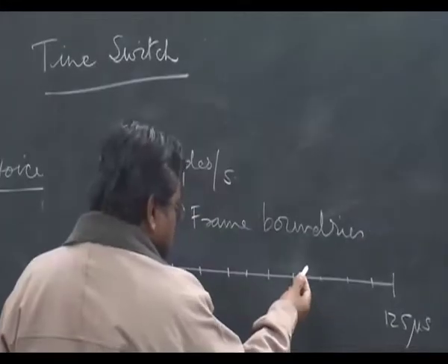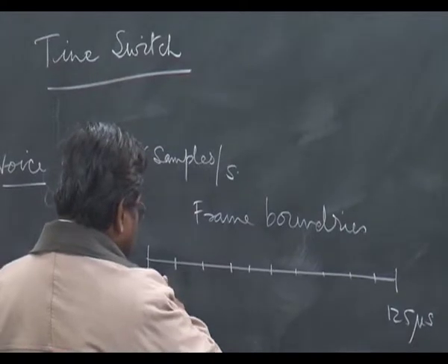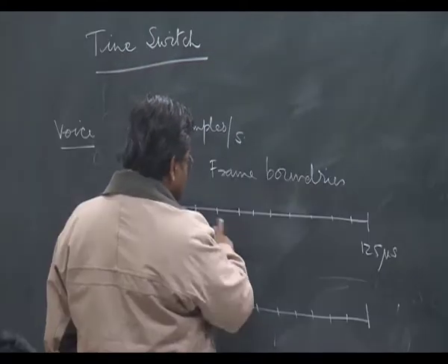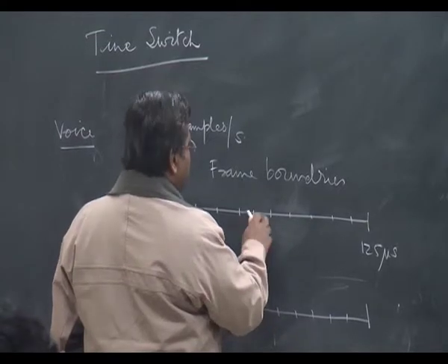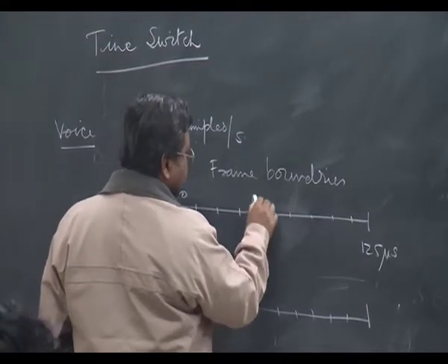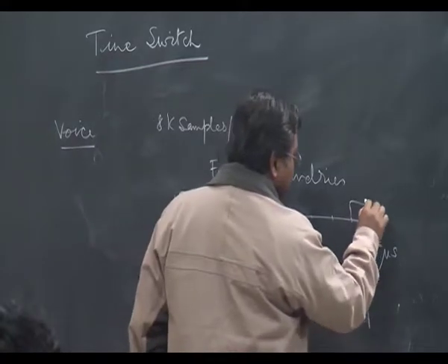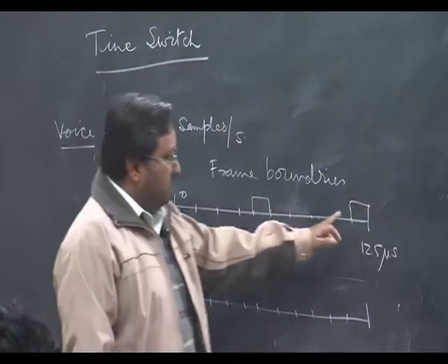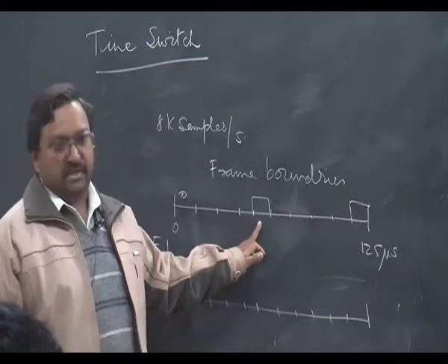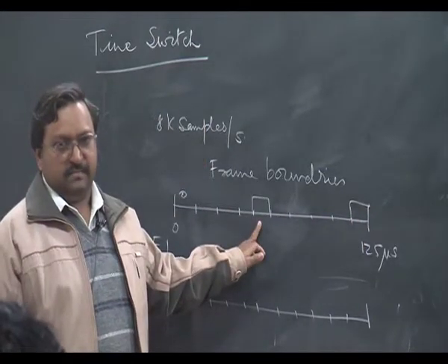So usually in this case, numbering from 0, the 16th slot and the 0th slot are used, one for framing purposes and one for signaling purposes. That is the way it actually is.